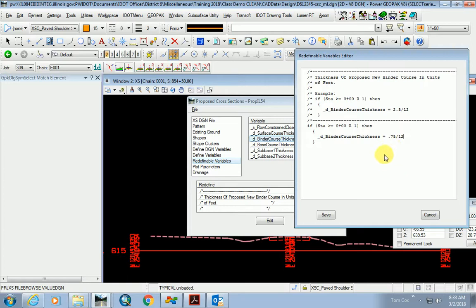But on a lot of projects, including this one, because this is a real-life project, our materials section did give a pavement recommendation of going with an extra thick overlay. Isn't that right, Clint? What was it, like 2 or 3 inches on the binder, maybe? It was like 1.5 inches? Yeah, I can't remember. Probably 1.5 inches and 1.5 inches. So your total overlay thickness was maybe 3 inches instead of 2.25.